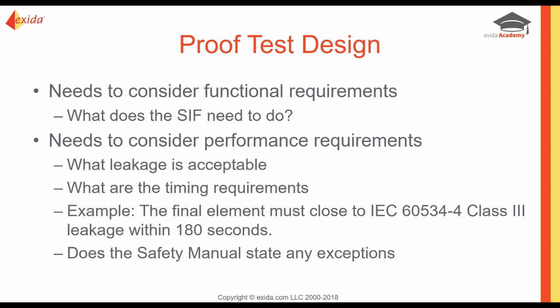Say there's a problem and it needs to shut down the process. What does your SIF need to do? Does the sensor need to detect something? Does the logic solver need to figure out it needs to act? And then the actuator needs to close the valve. So the functional requirements would be that valve closing. It will shut off the process flow.